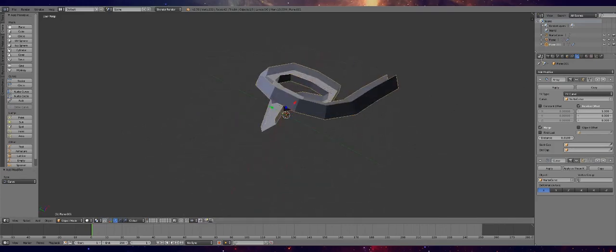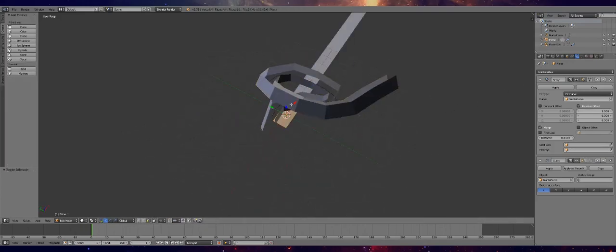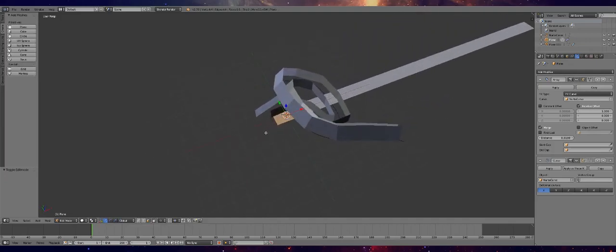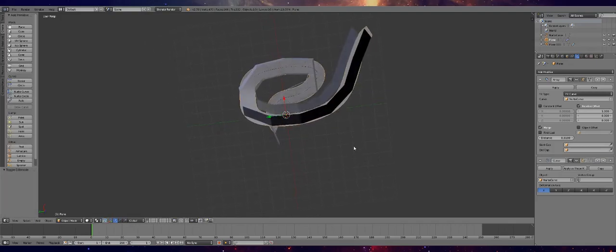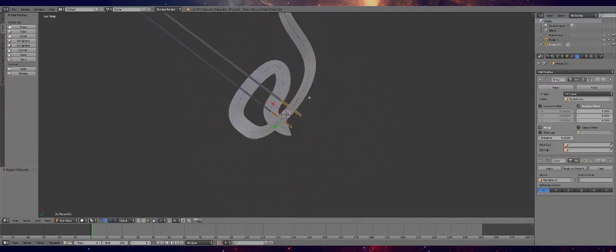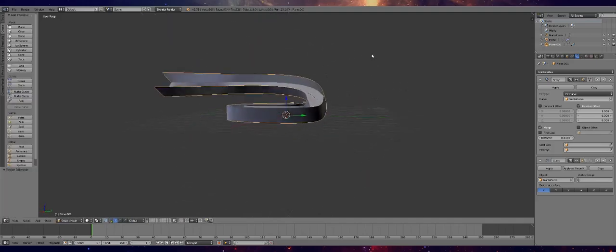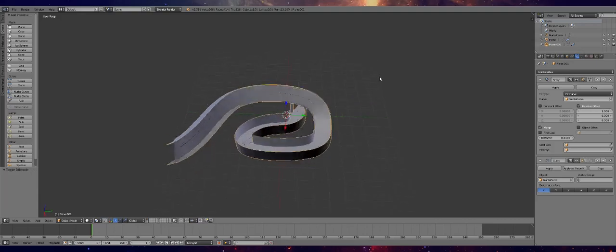So the first way to fix this is by making sure your object is not super large on your x-axis. So I'm gonna scale that to like 0.1. So you can already see that my floor is way smoother. So I'm gonna do the same to the walls because they need to fit the same way. And now we have a slightly better version.